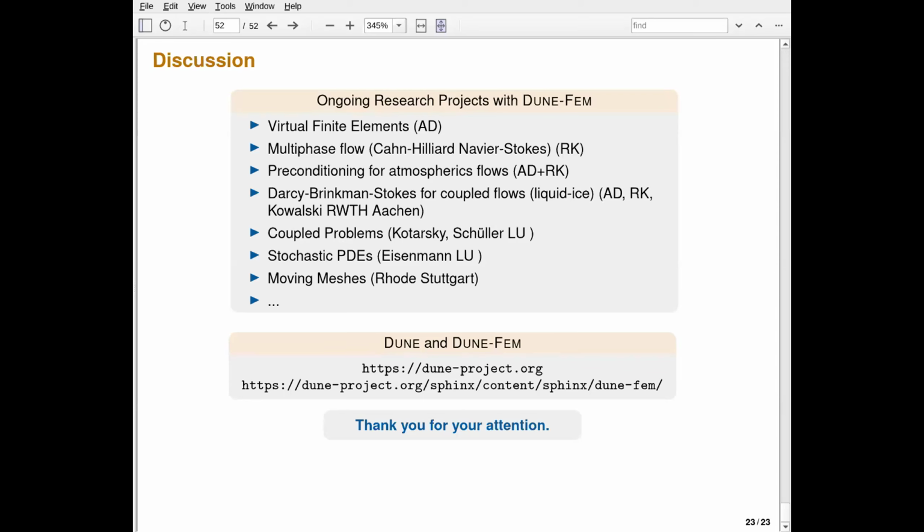Yes, so we have quite a variety of mesh elements. Standard ones, of course: triangular, quadrilateral, or tetrahedral and hexahedral in 3D. There are some grids also providing prismatic or pyramid elements.